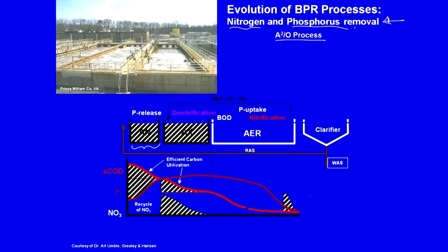And why is it relatively better? Because as we looked at it in the case of nitrogen removal, with the internal recycle, the nitrate concentration that goes through to the clarifier and is returned to the anoxic tank will be relatively lesser. That is what you see, recycle of NO3, let us see, right. So, that is going to be pretty less. So, the anaerobic conditions are pretty well maintained, no source of electron acceptor like NO3 minus or such, let us see, right. And what else is happening out here?